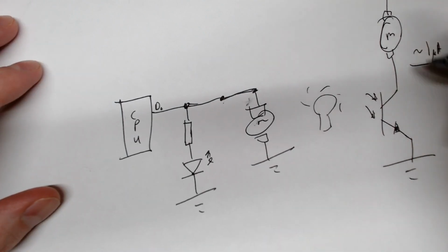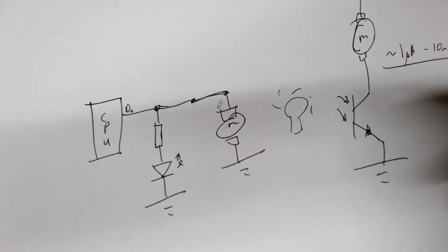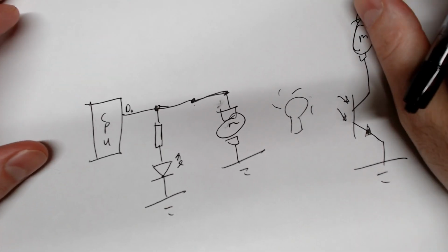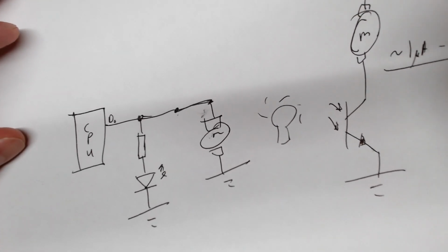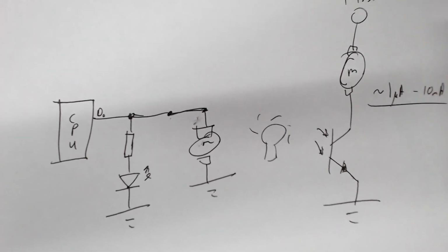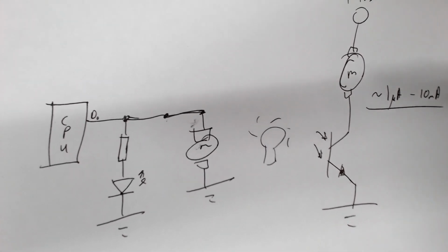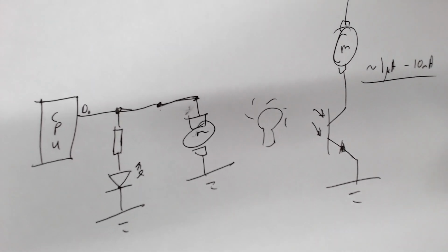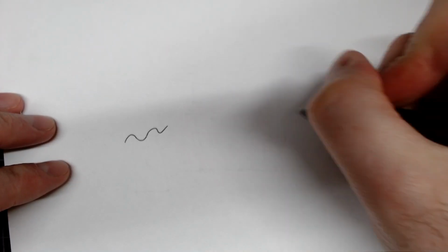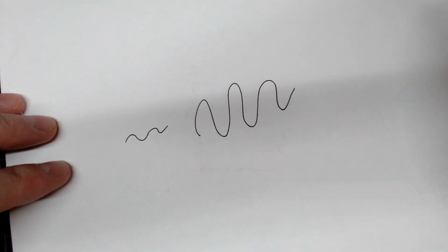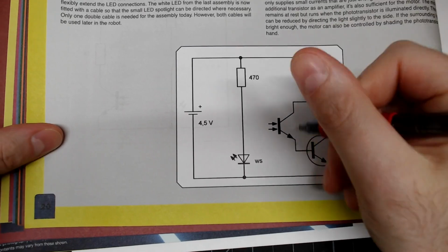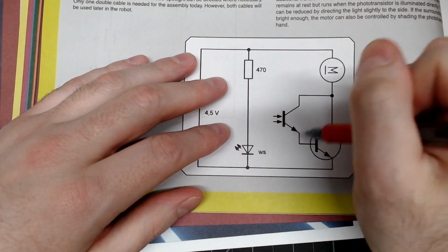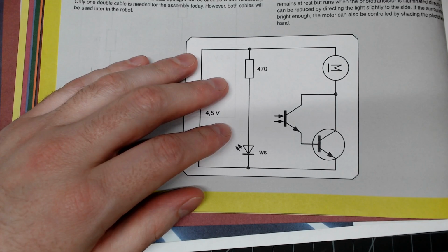So the whole point of a transistor, of an actual real transistor, I should say, or a power transistor or an amplifying transistor, or something that is meant for this, one of the transistor's purposes is to amplify current, or to amplify the signal that's going through. So a common use case is you have some signal that's coming through and you want to make that signal bigger. And that's essentially what we're doing. We can't source a lot of current coming from this phototransistor.